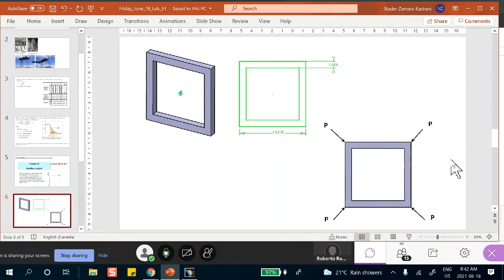The same thing applies when we calculate natural frequencies. You suppress modes, for frequency, for vibration, which is not what we're doing here, or for buckling. So if you're using planes of symmetry in buckling to reduce your model, be aware that you get what you pay for. In other words, for that mode of deformation, you get a non-conservative buckling load. But this can also buckle well below that load out of plane, when symmetry is not taken into consideration.